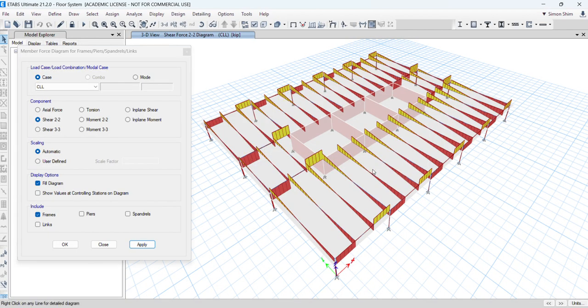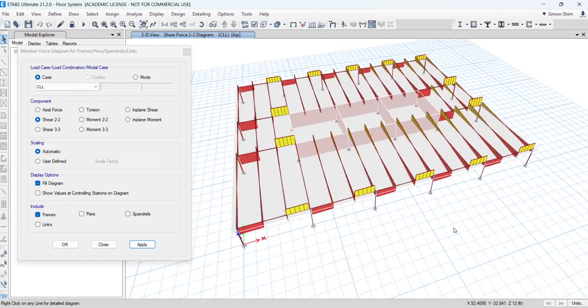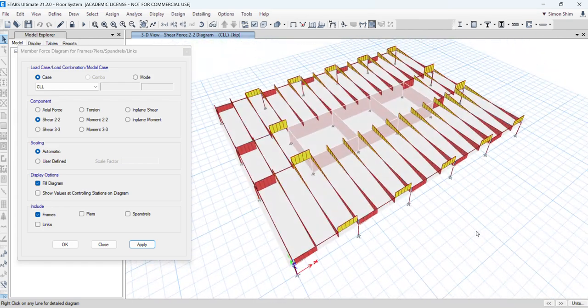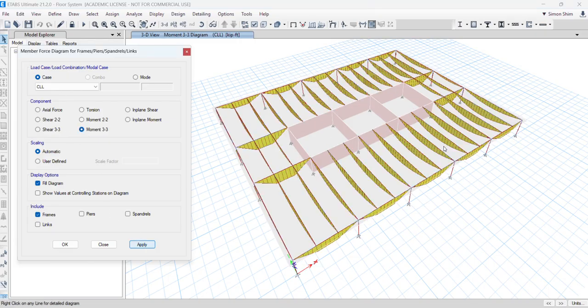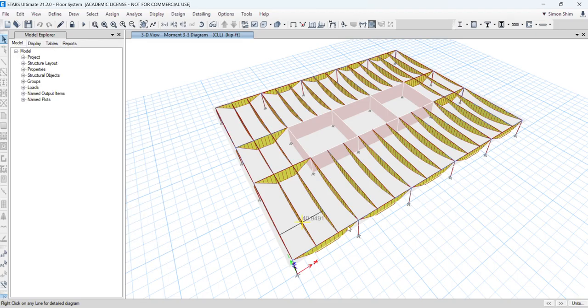This is actually basic beam analysis, which your structural or steel class will teach you. Now you should be able to calculate the maximum midspan moment based upon your uniform loading times tributary width, so WL squared over 8, which gives you the maximum moment at midspan.